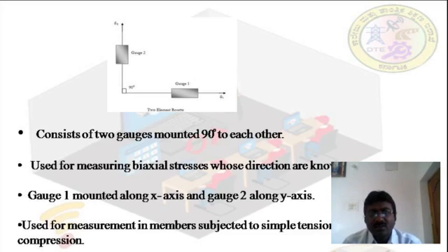So now let us see what is biaxial stress. Biaxial stress means the stresses that act in planes at right angles. The term biaxial suggests 2D analysis, that is, two-dimensional analysis of the stresses in the xy plane. And the stress normal to this plane is assumed to be 0. The biaxial stress is a common occurrence in most of the structural parts.